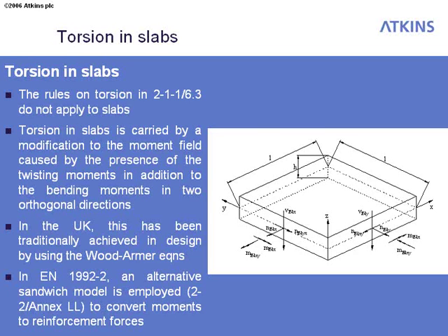Basically, for things like bending, we distribute the bending moment as a push-pull force in the two layers. Torsion will be distributed as two opposing shears in the two layers. And then there's a set of equations that we use to work from just the in-plane forces in each of the layers to turn them into reinforcements. And what you'll find is we get very, very similar answers to Wood-Armer doing that.